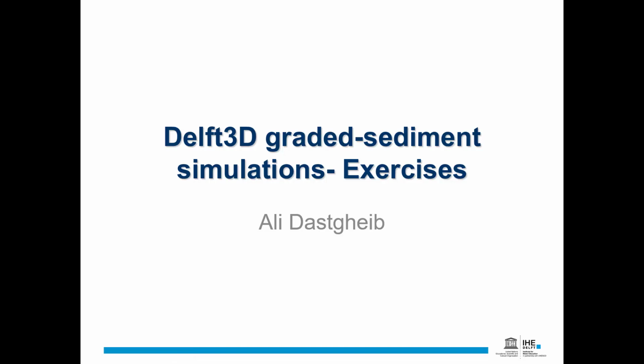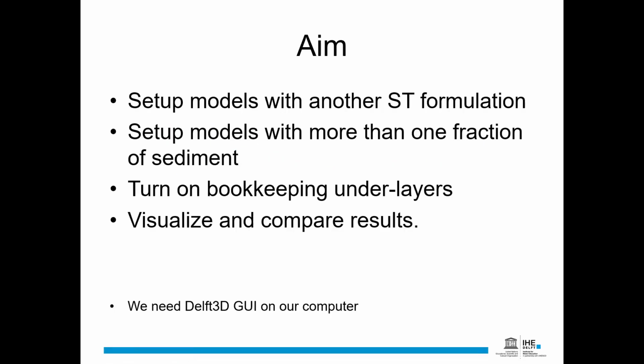Good day. Following the lecture on Delft3D graded sediment simulations that we had before, which described how this is implemented in Delft3D, in this lecture we want to do some exercises with those types of models and simulations. The main goal of this set of exercises is to set up models with another sediment transport formulation, set up models with more than one fraction of sediment, turn on bookkeeping underlayers in the model, and visualize and compare the results and see the effect of the changes that we have made in the different simulations.